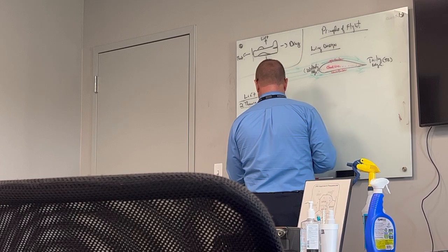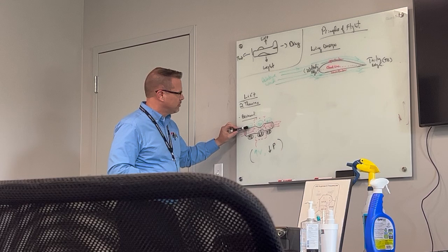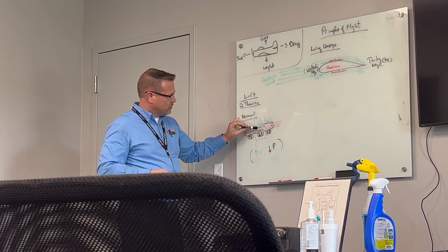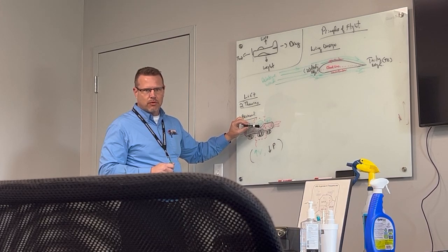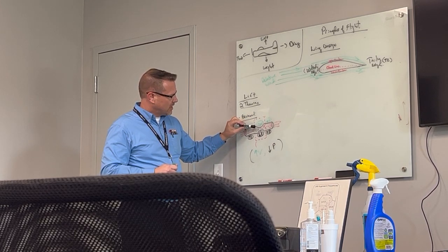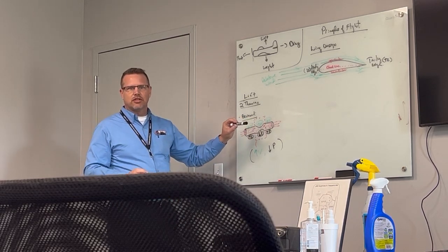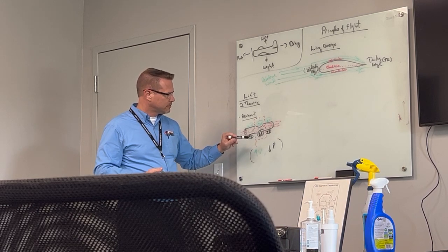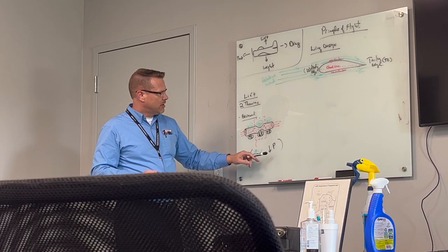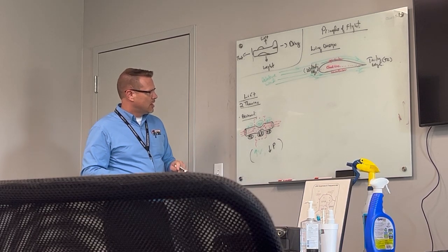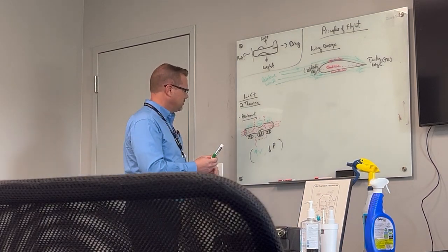So what happens is, in order for this fluid, there's a large mass of fluid that's constantly putting through here. In order for all those molecules to get through that smaller space, they need to speed up to all fit through that smaller space, right? And as they do that, the pressure of the overall fluid ends up decreasing because of this acceleration of the molecules that going through this constriction. And so from Bernoulli, we have basically as velocity increases, pressure decreases.